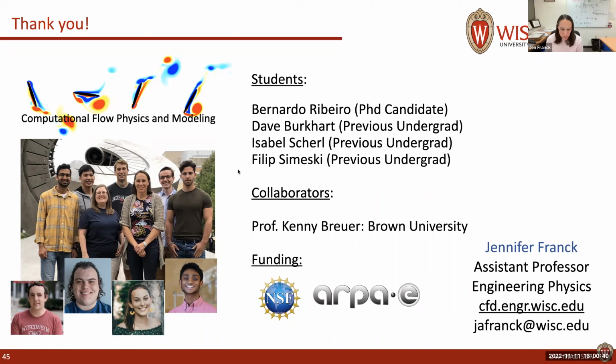Yeah, 3D, we are not so much interested in 3D because the long slender blades give us relatively two-dimensional flow. So even if we go to 3D, it's kind of to increase the Reynolds number and do a three-dimensional large eddy simulation, but we're not interested in tip effects on the blade, for example. That's something that we could put end plates on and mitigate. You think the wake becomes inherently 3D though? So that's something we have looked at. We've looked at that in the flume as well as in our LES to see what kind of three-dimensional instabilities might exist as the Reynolds number increases.